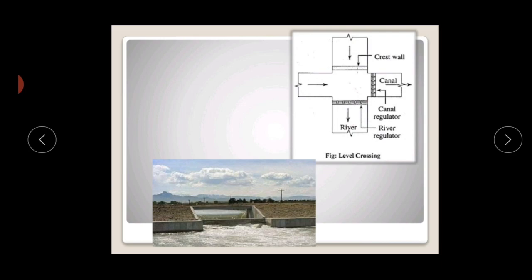That is, we are going to control the discharge passing into the drainage. At the outgoing of the canal, a regulator is also provided so as to control the discharge into the canals. In this arrangement, a perennial drainage discharge is sometimes advantageous, used so as to augment the canal supplies.